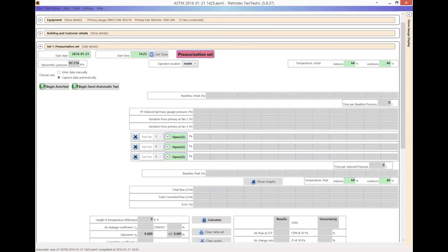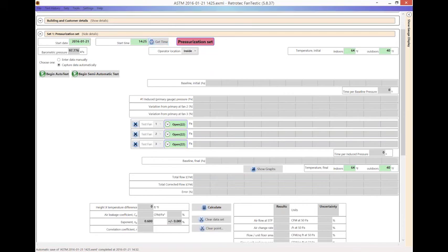So let's just go through again some other stuff that's on here. It's got my date. It's got the time. It asks where the operator is located. Sometimes you may do a multifamily, and it's easier to be outside controlling this versus inside, and all of your fans are directed a certain way. We can talk about tubing later, but this wants to know where you're located. Usually that is also where your gauges are. So I may be outside, but your gauges may be inside. It also wants to know where your gauges are located.